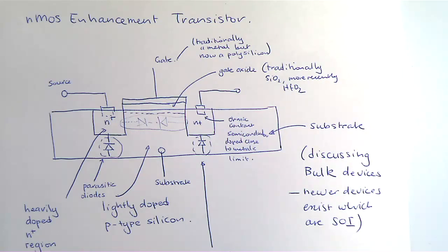Okay, because you don't want conduction into the gate itself. You want to make the gate high impedance, right? That's one of the reasons. Okay, and then also metal on silicon, you also get some implantation, which causes problems, right? So you put an oxide, and then what you do is you deposit a gate.